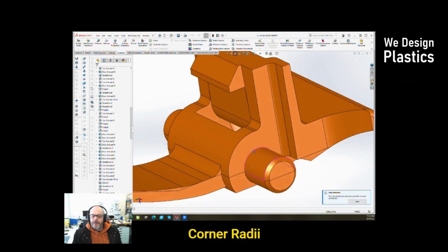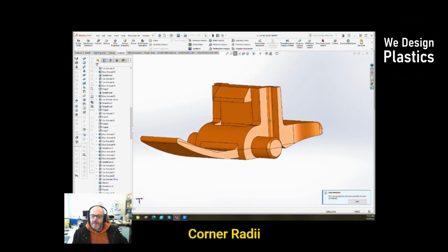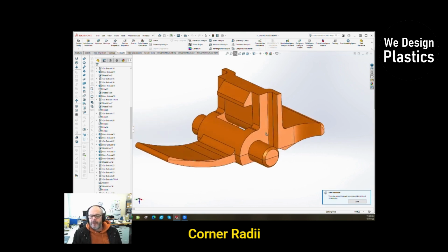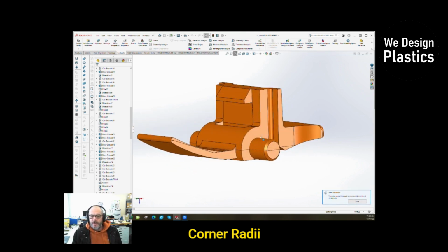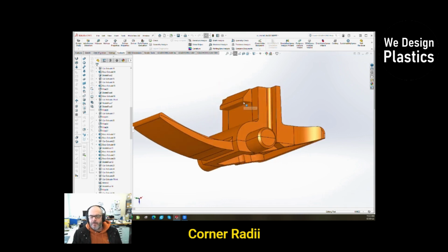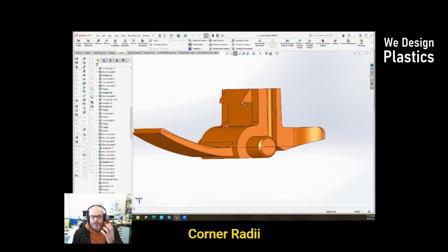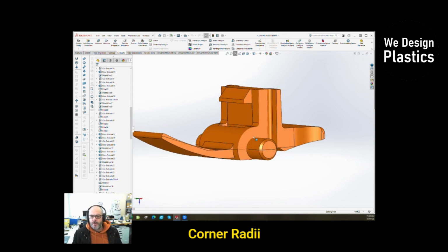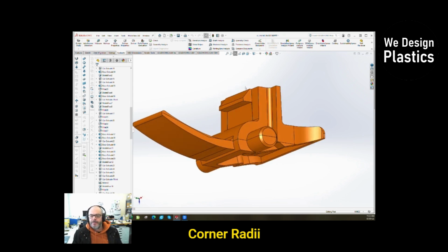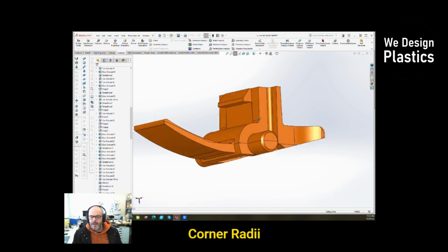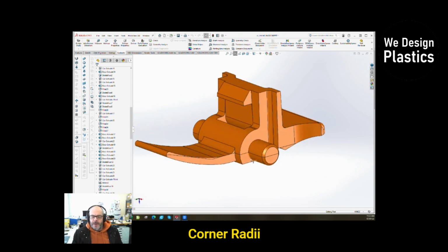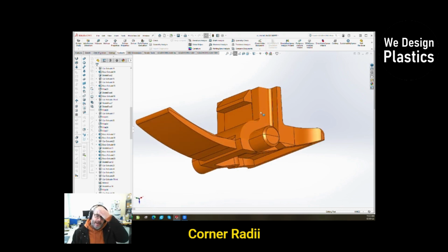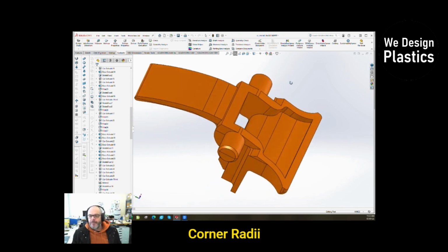that can cause fractures. The other area that's going to be stressed on this part is between these diameters when it's pivoting on this latch. If you pull on, there's actually a door that this attaches to. If you pull on the door, it's putting pressure between the diameter and the latch. This latch under here's got a sharp corner that could fracture through there. These could fracture around there too, so they're prime candidates for radiuses being required.